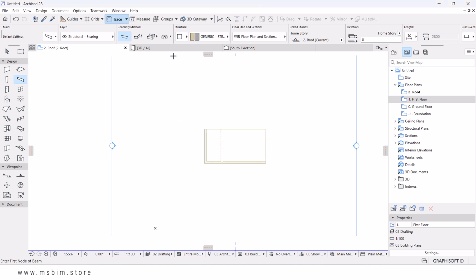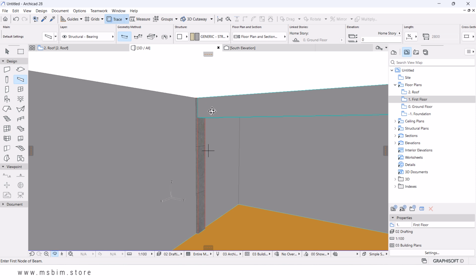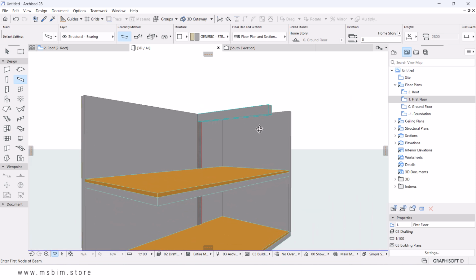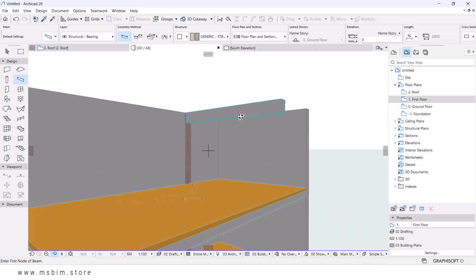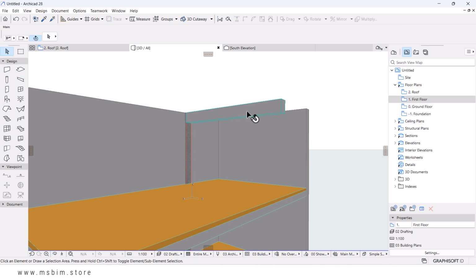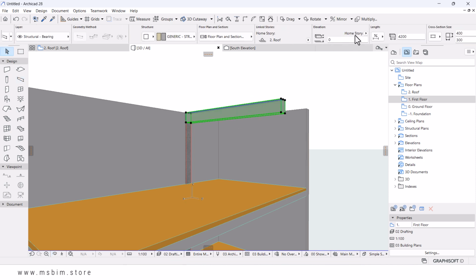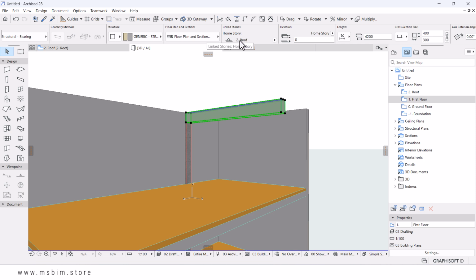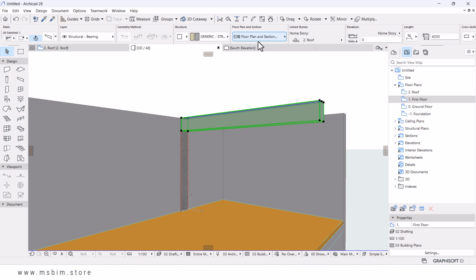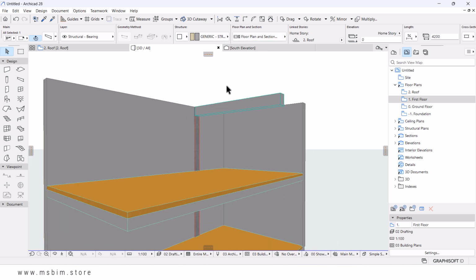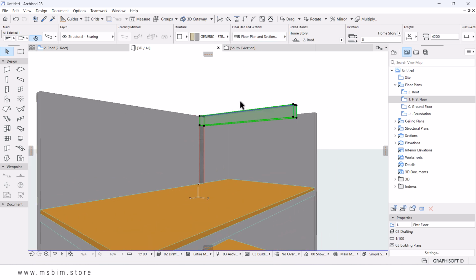So if you check on 3D, you would see it's here, and it's accurately positioned. I don't know why it was asking me to check that. We can also check the linkage, that it is sitting on the accurate level, which is fine. So from here we have to key in the roof pitch for our structure.